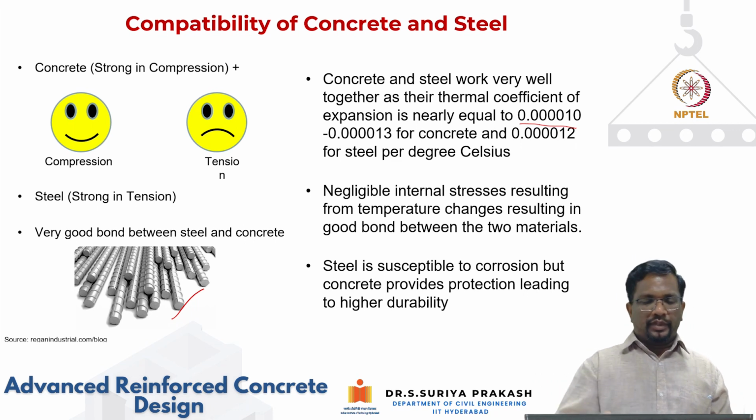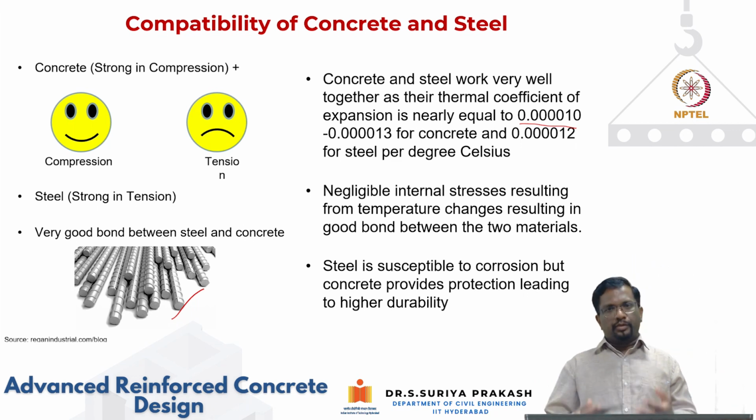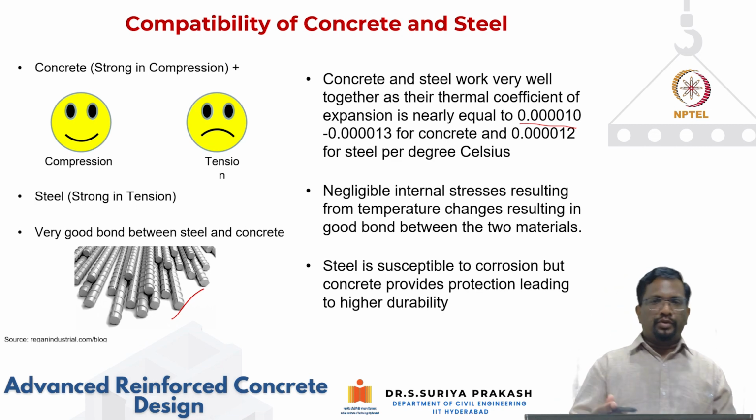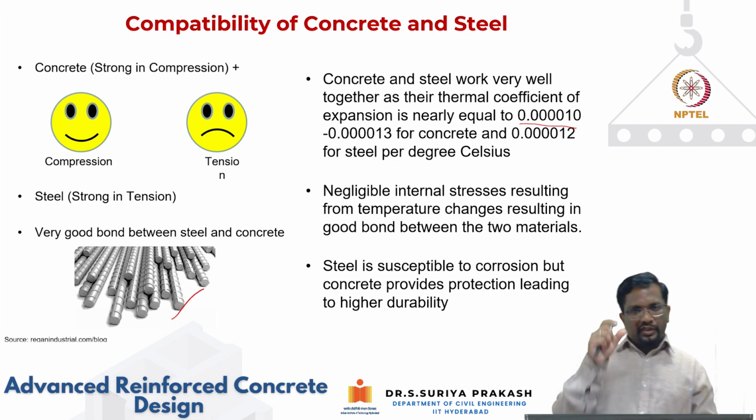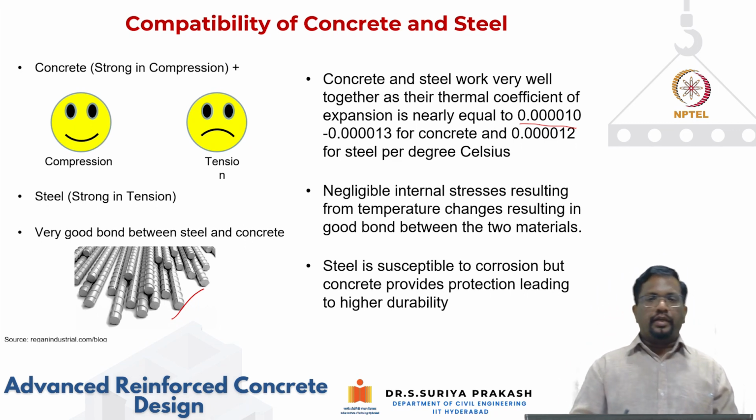And steel, when used as a reinforcement, again is susceptible to corrosion. We'll talk about it in module 3, where we'll talk about the durability aspects, what all the things that we need to consider, right? So steel is susceptible to corrosion, but however, if you design the concrete well, it can really protect the steel, and it can lead to better durability.